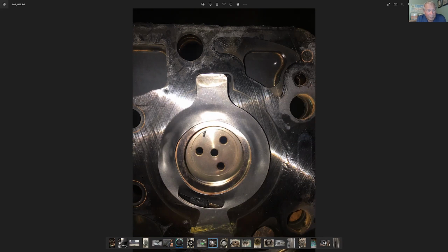I do know when they do the flood start test at Copeland, they'll start with a 25% overcharge, just as an example on their test board, and then they'll see what the effects are. Then they go to 50% overcharge, and they'll do 25 starts at that. Then they'll go to 100% overcharge, and they'll basically start it until it breaks. I've seen the guys do those, and they're pretty durable machines. They'll take it for a bit.